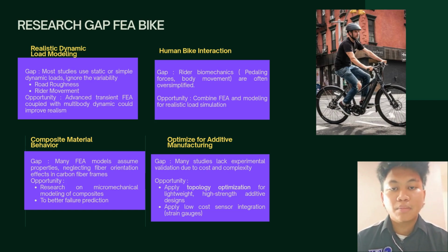So next, dynamic and fatigue analysis. Moving beyond static, dynamic analysis is crucial. This simulates transient impacts like road bumps, drops, and sudden forces, which are vital for assessing the frame's overall durability and response to real-world riding conditions. Furthermore, fatigue analysis is indispensable. It predicts long-term failure that can occur due to cyclic loading such as repeated pedaling or constant vibration over extended use. This ensures the frame maintains its integrity and safety throughout its lifespan.